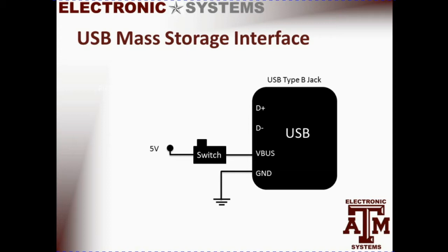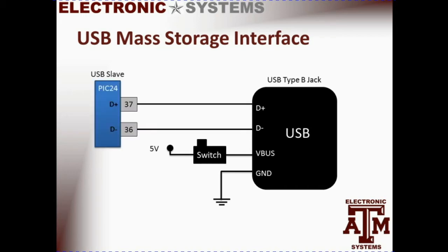In addition, there are 2 wires that are used for communications from the NanoRacks chassis computer to the NESI board. The PIC-24 is programmed to be a USB slave and allows the NanoRacks chassis to access the onboard SD cards of the NESI board.